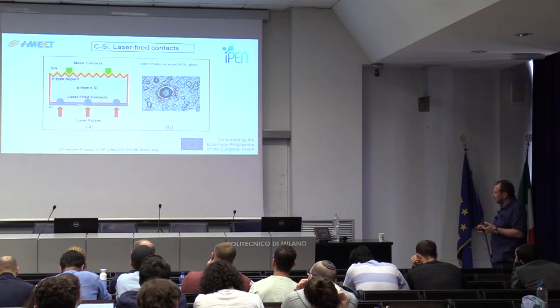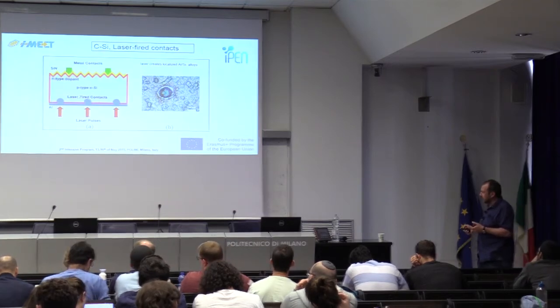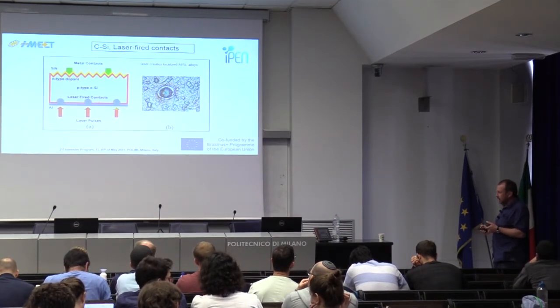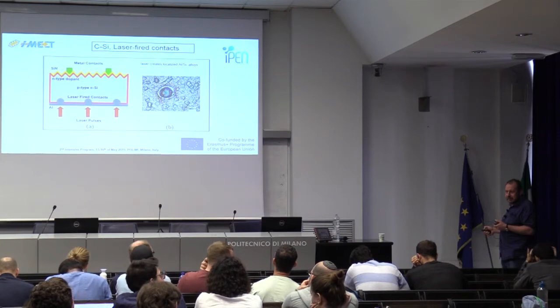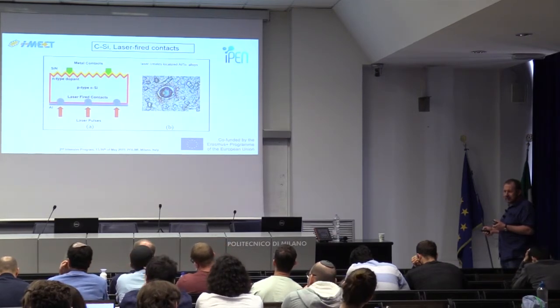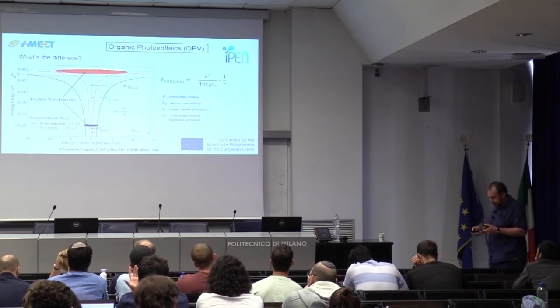So you can put a thick layer of aluminum, heat it up, and aluminum will diffuse into the silicon. But you can improve or increase this process also by locally melting the aluminum layer, and actually it's remolten together with the silicon, and this again improves the contact in the silicon.